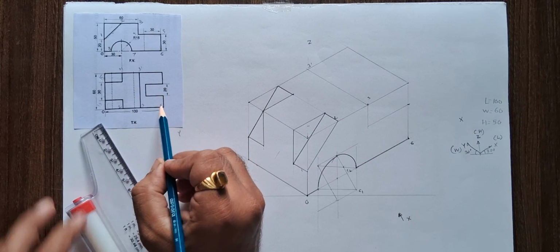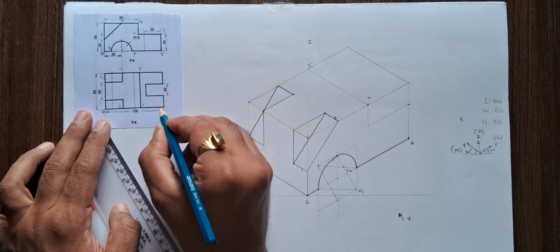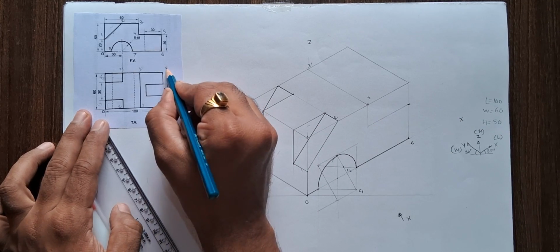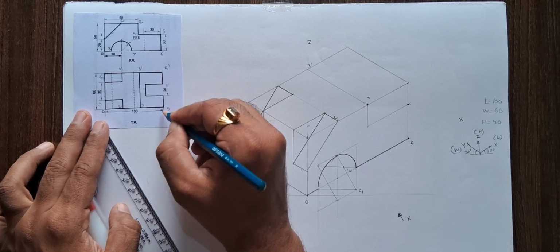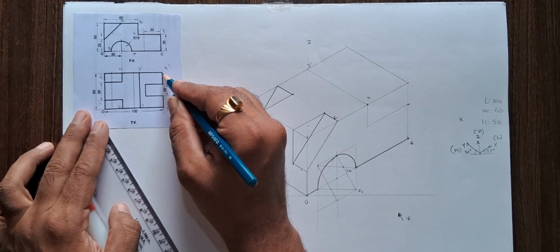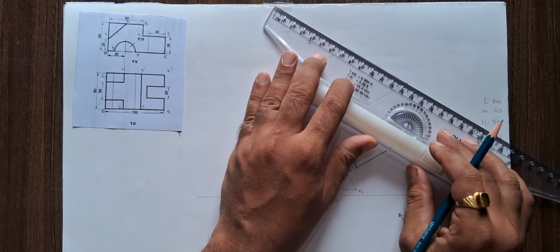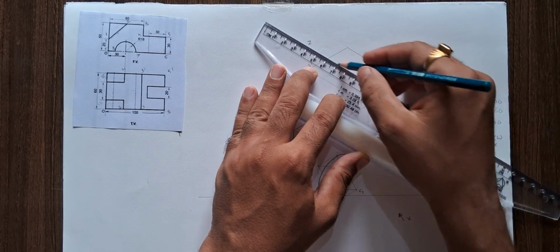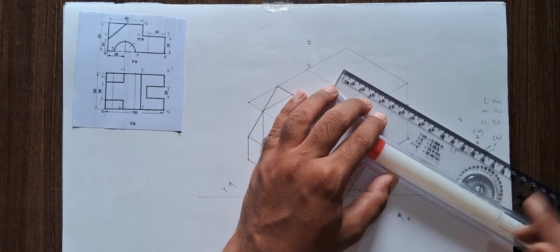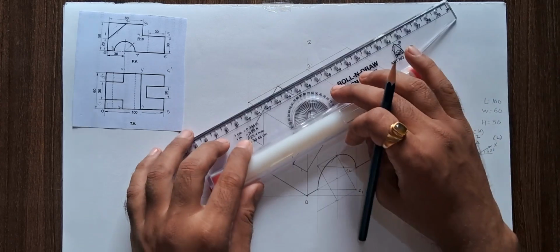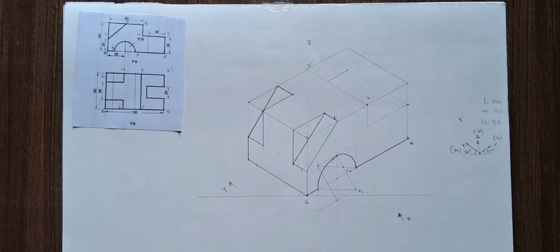Now at the back side, you can see there is a slot of distance 20 mm. So from this point, this is point number 5, and this is 5 dash. In between 5 and 5 dash is 60 mm from the front face. This total distance is 60 mm. In between 5 and 5 dash, there is a gap of 20 mm. So we can add this roller along the B direction, and we can draw a 60 mm line, because the width of this object is 60 mm. And from this end point, we can directly draw a line up to 3 dash.